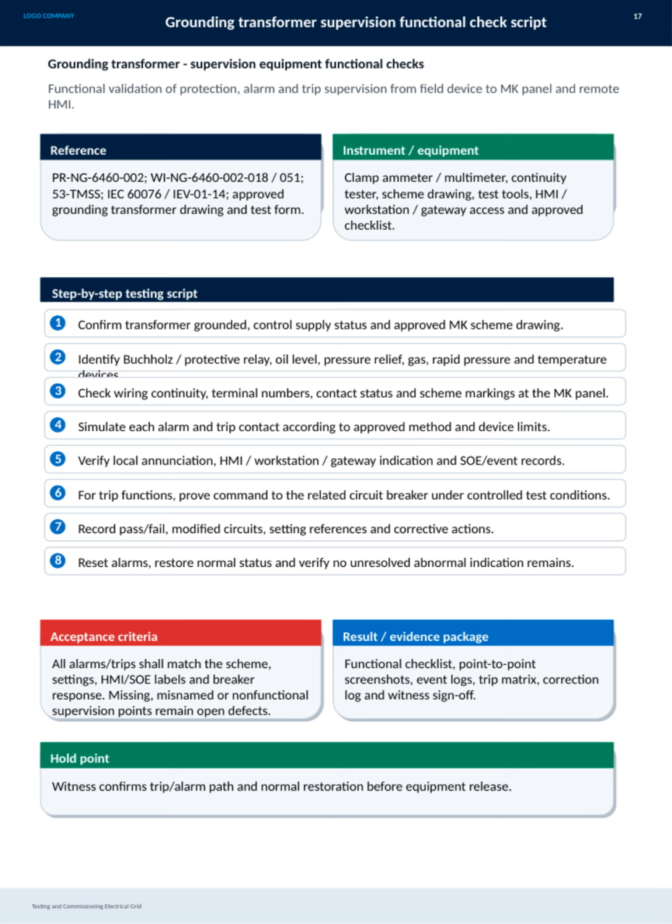Finally, alarms are reset, normal status is restored, and we confirm no unresolved abnormal indications remain. The acceptance criteria are strict. All alarms and trips must match the scheme, settings, HMI labels, and breaker response. Any missing, misnamed, or non-functional supervision points are considered open defects.